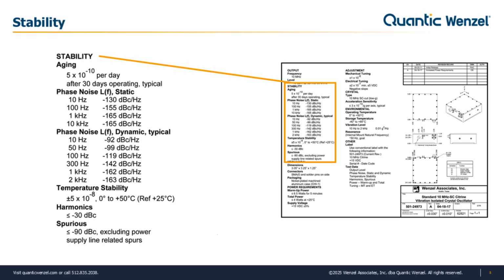In telecommunications, the fundamental frequency is also referred to as the carrier frequency. This is why power levels of signals which are being related to the power level of the fundamental frequency will be denoted by dBc, with the C meaning carrier. For oscillators designed to operate in both static and dynamic environments, phase noise specifications are listed for when the device is in a still environment and when the device is subjected to random vibration. The frequency bandwidth and power spectral density of the environmental vibration for which the oscillator is designed and tested to operate can be supplied by the customer.